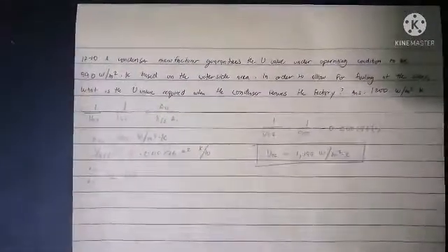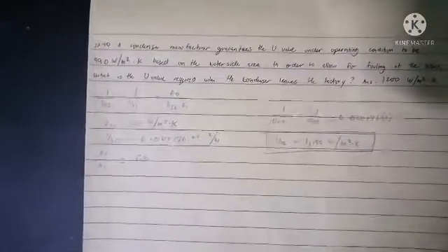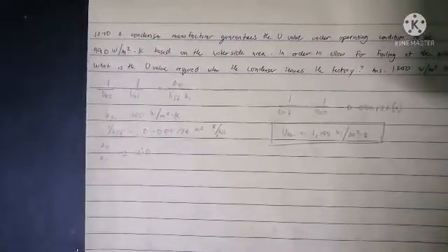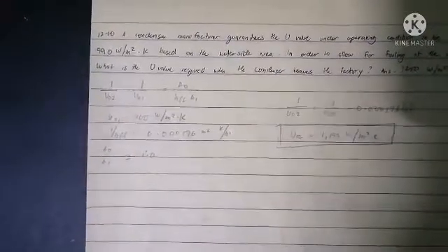So chapter 10, problem number 10. A condenser manufacturer guarantees the U value under operating condition to be 990 W per m squared Kelvin based on the water side area. In order to allow for fouling of the tubes, what is the U value required when the condenser leaves the factory? So 1 over U_O2 equals 1 over U_O1